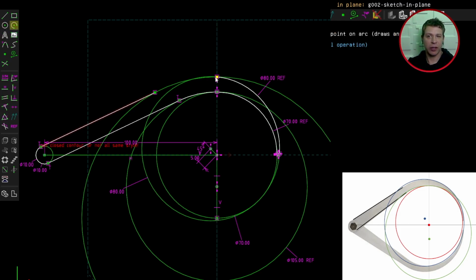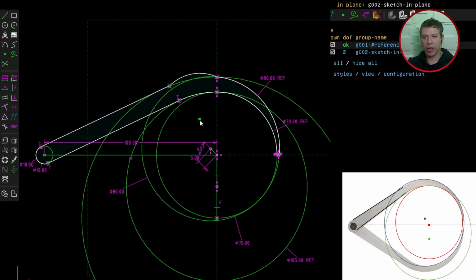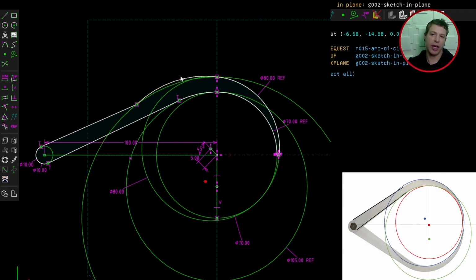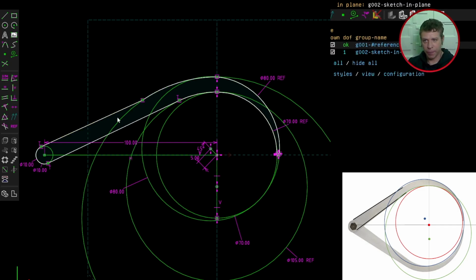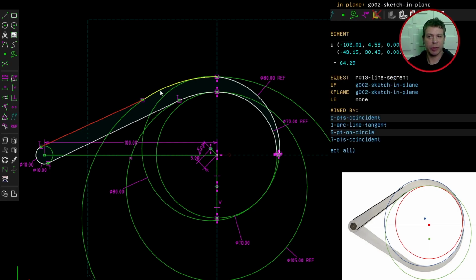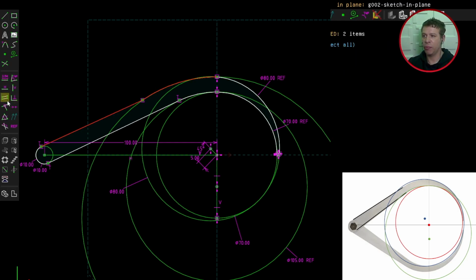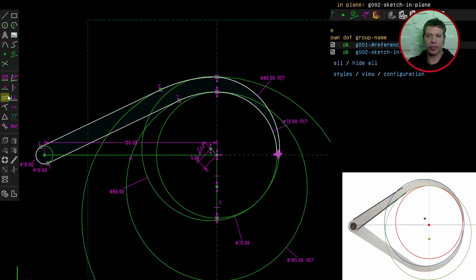And then I'll complete the contour and I'll drag this down. I want this arc's center to coincide with that point. Select them both and click constrain to be vertical. We've got 1 more degree of freedom, and that's because we need to constrain this line to be tangent to that curve. I'll select them both and click constrain to be tangent.